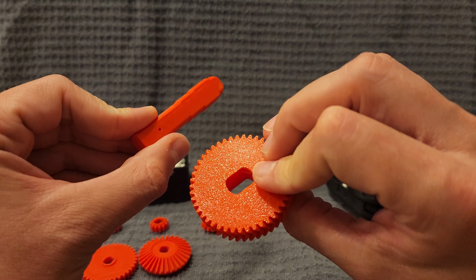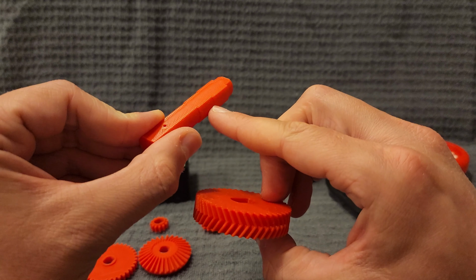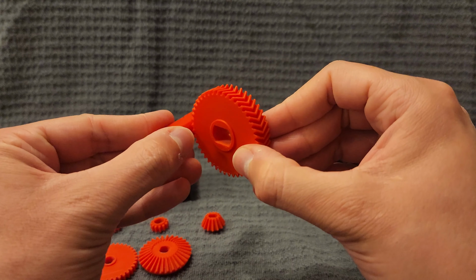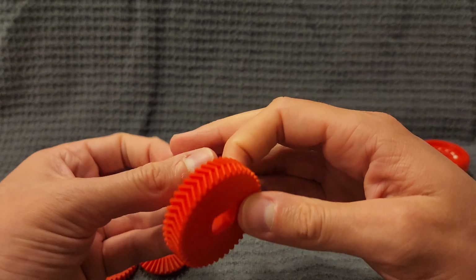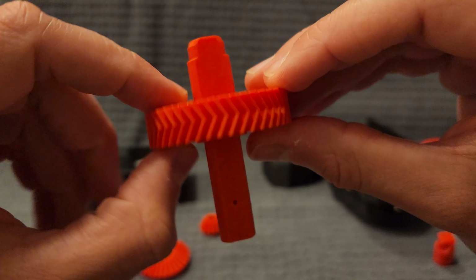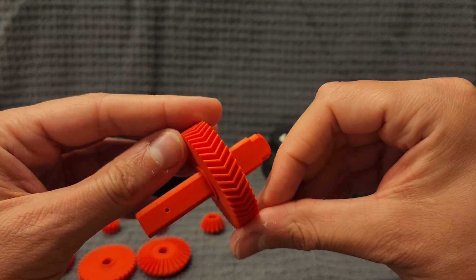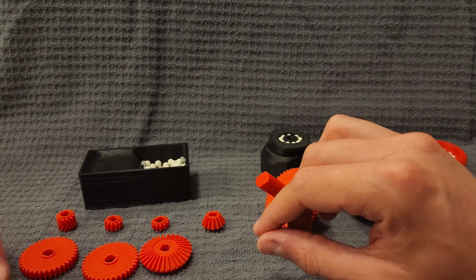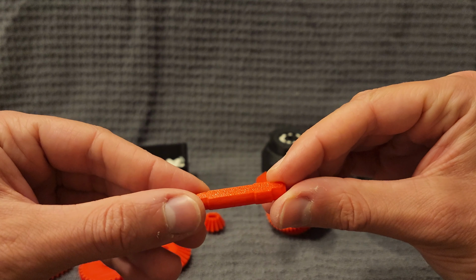It's important to essentially put the side of the gear that has no bump, as you see here, towards the step on which the gear is going to rest. So the bump always has to face towards the end of the shaft, as you can see right here. So the first shaft is now assembled. Let's move on to the second one.